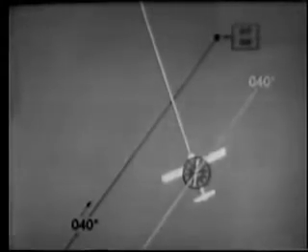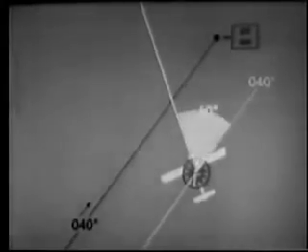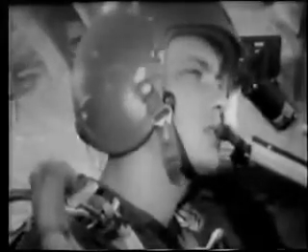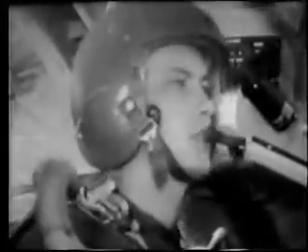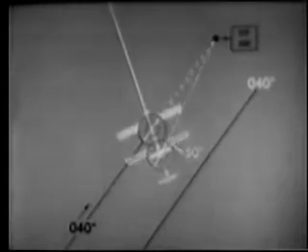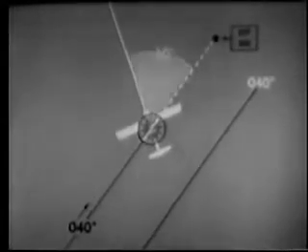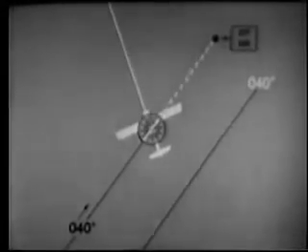Now we must think ahead. What will the ADF indicate when we reach our new track? Remember, we turned away from our parallel heading 60 degrees, so we will cross the new track at a 60-degree angle. He isn't quite sure. He's thinking. Will it read 60 degrees right of the nose? Sure it will. It must be deflected from the nose of the aircraft an angle equal to the interception angle.